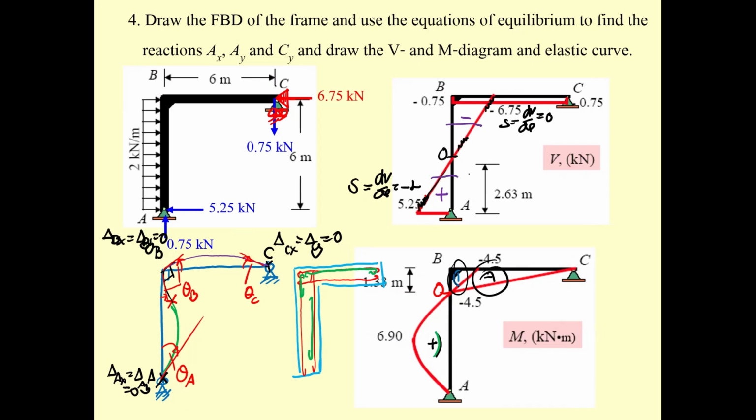But you have to think, this portion has low shear strength. So the spacing of the stirrups at the middle of the column may be large, and the stirrups close to this area and this area, you may put closer than at the middle.